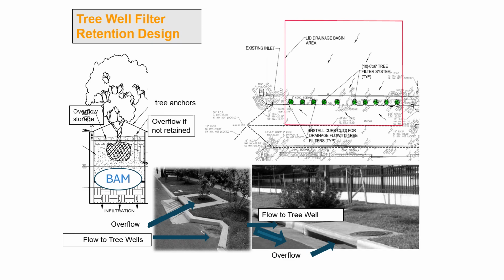It's also important to note that these tree wells can be designed to function in areas with high water tables. In such scenarios, they operate more as detention systems, temporarily holding water before a controlled release or overflow, rather than relying solely on infiltration for retention.